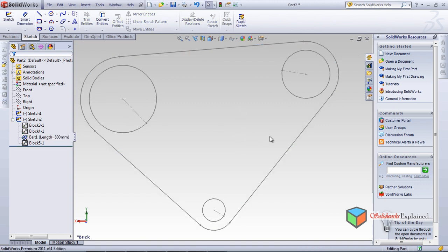So this is how your traction options are: traction between 2 wheels, traction between a wheel and an edge, which is a rack and pinion, not only the wheels but also the pulleys, between 2 pulleys, between 3 pulleys, the normal belt when it moves as it is shown, not only the normal belt but the cross belt where one moves clockwise and the other anti-clockwise. So in this way you can simulate many things.